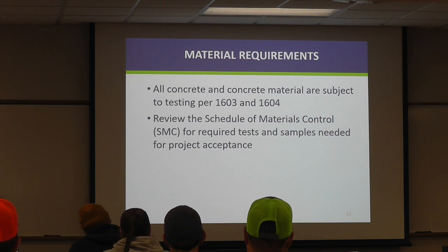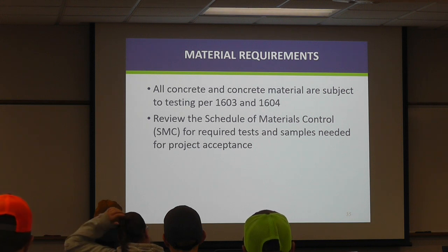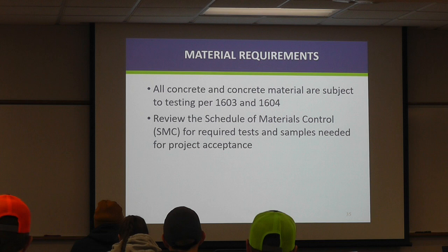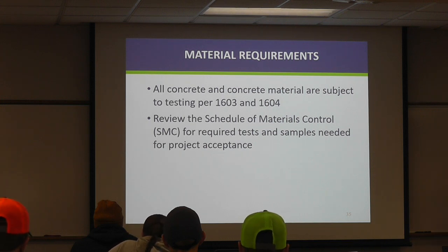Okay, so what are some material requirements? Concrete and concrete materials are subject to testing per 1603 and 1604. Part of that says you are required to review the schedule of materials control for the required tests and samples needed for project acceptance.